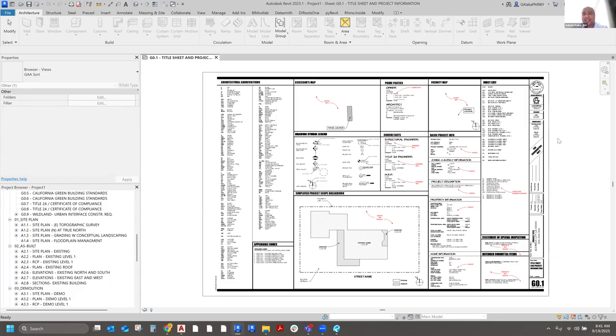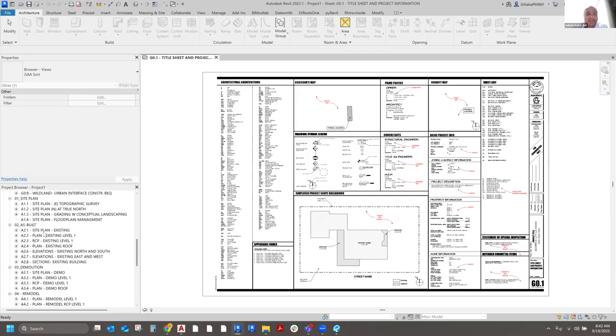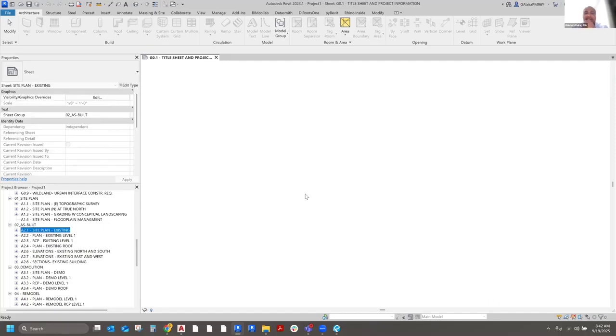And going back to BIM, Revit is a very smart software because you can phase things. In Revit, I can model the building in its existing condition, and that's going to be called the existing phase. And then I can demolish walls. So I can say, demolish this wall, demolish that wall. And then if I change my phase, those walls will disappear as if I'm actually demolishing them. So Revit keeps track of that, and I'll show you a quick snippet of what that looks like in a little bit.